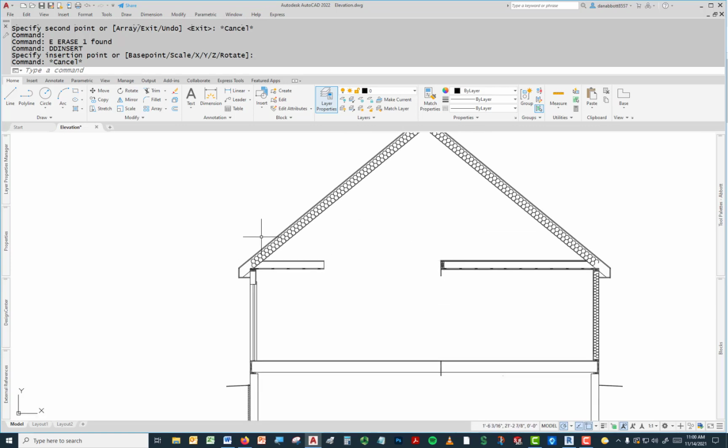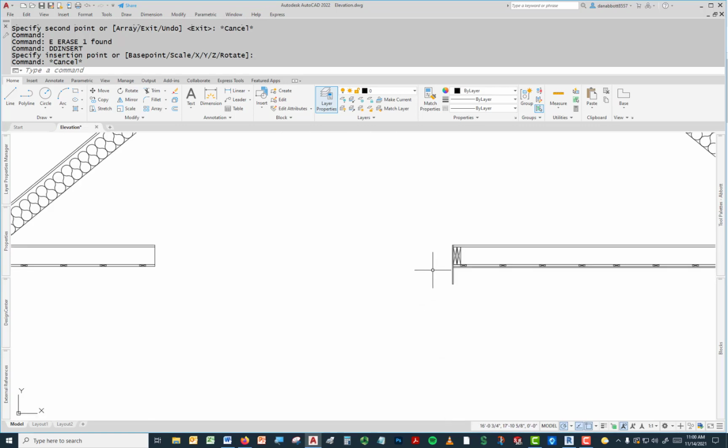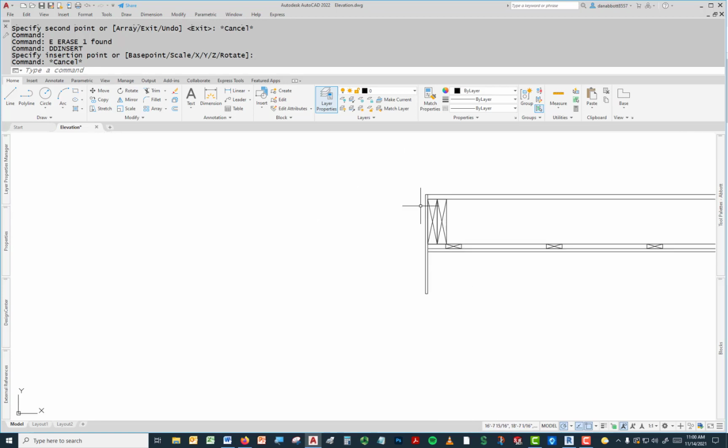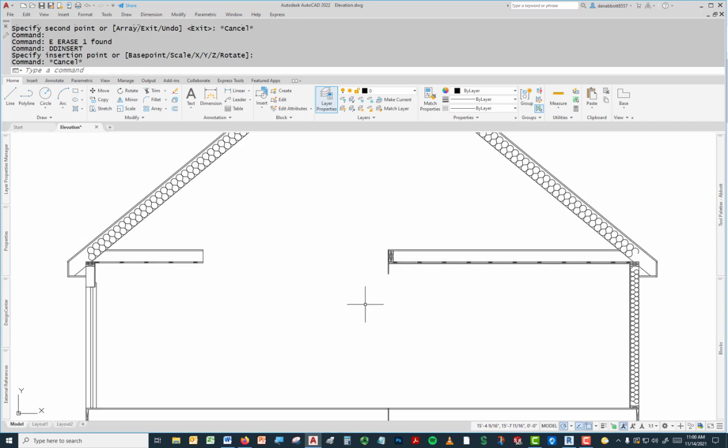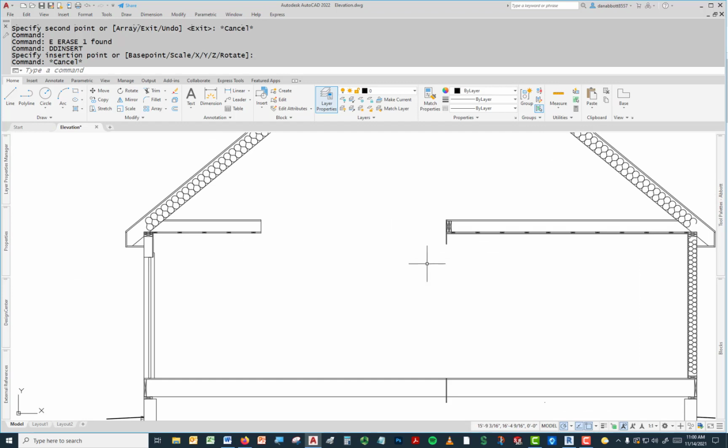Now, I've got this framed out. Obviously, I'd have some more over here as well, but I've got this framed out. You've got your header, and I've got a piece of plywood here. That piece of plywood is essentially a gusset. This is the way I would do the stairs. I want them to end up level with this, but rather than have a stair up here, or a tread, I'm going to go up and just put a little nosing on this. And then what I'd like to do is have it generate the stringer, drop the stringer, put a little kick plate in it, and I want to be able to tell it what I'm hoping to do